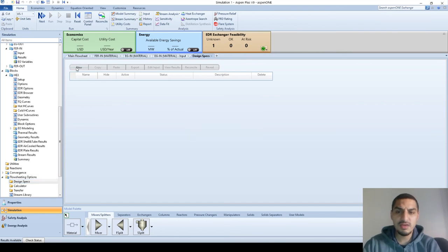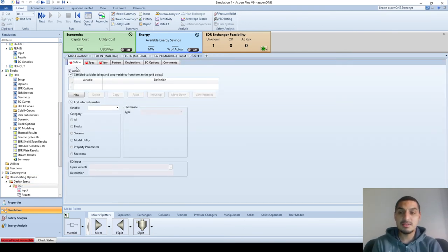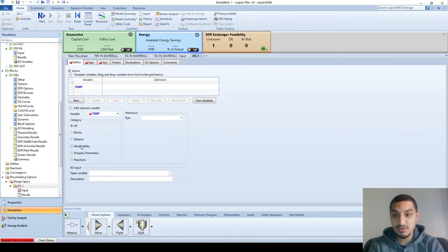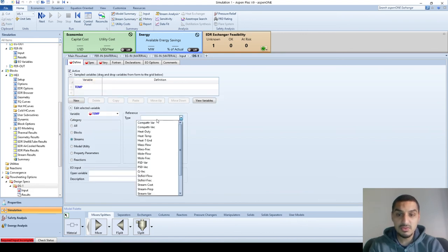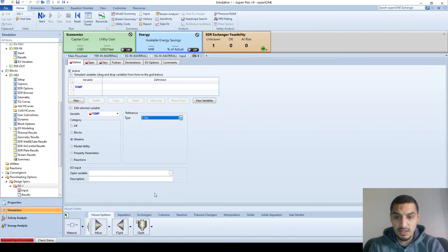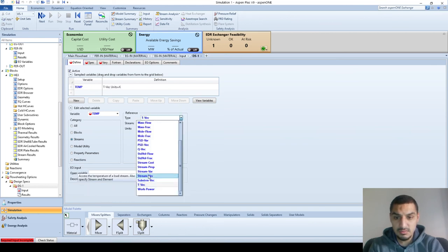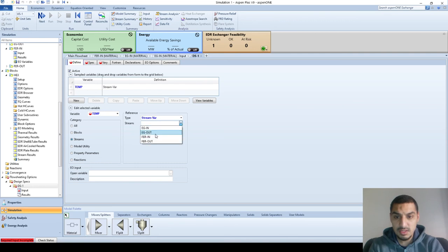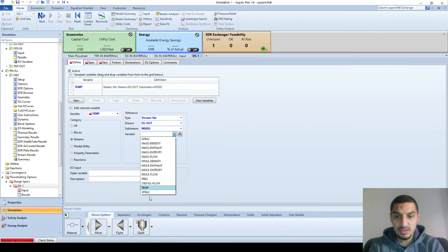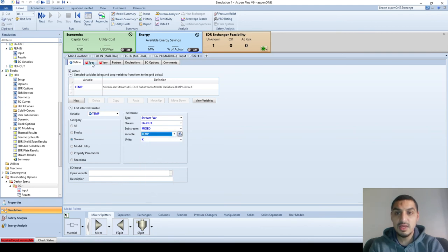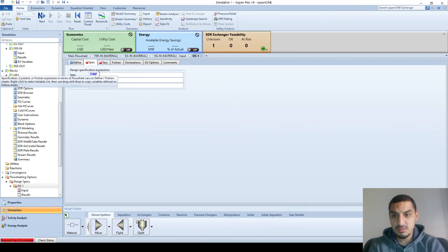So in this case, we have a parameter that we change to set another parameter. The parameter of interest that I am interested in achieving a specific value of is the stream variable, which is the ethylene glycol out, and I want the temperature in Kelvin. Here I would set the parameter, which is temperature, to the value of 315 and the tolerance 0.01.